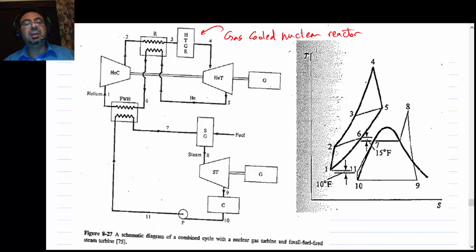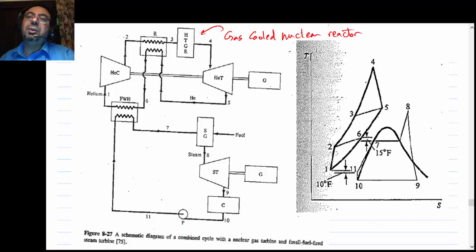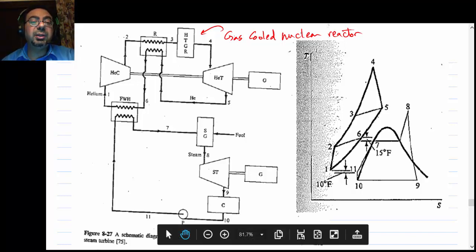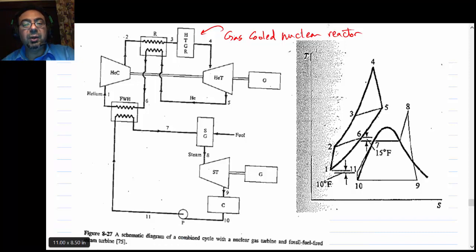Okay? And so a steam cycle by itself cannot peak more than what, 40 something, 45%? That's a steam cycle by itself. But when you put in a gas turbine and use the exhaust of the gas turbine to run the steam power plant, your efficiency goes up to like 65% or something. So the power plant in Owasso over here in Oklahoma has an efficiency of 65%, but the one in Jenks has an efficiency of 40%, more or less.